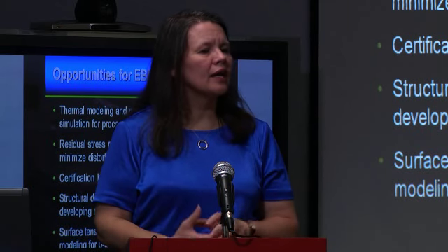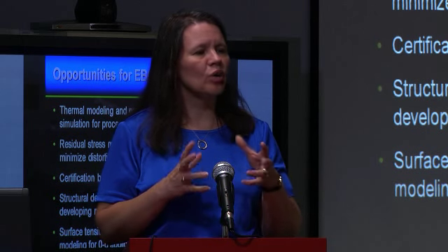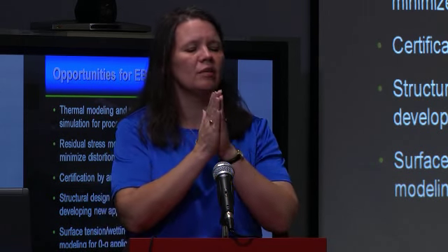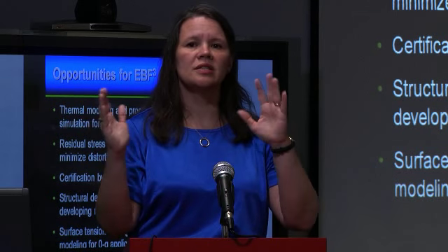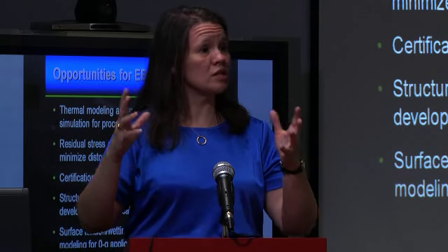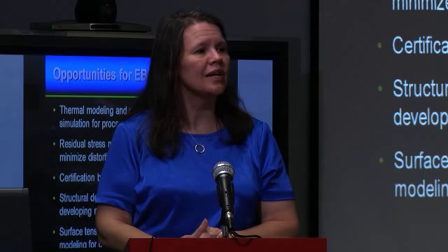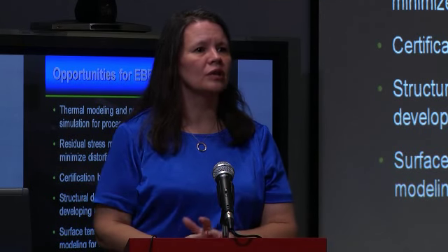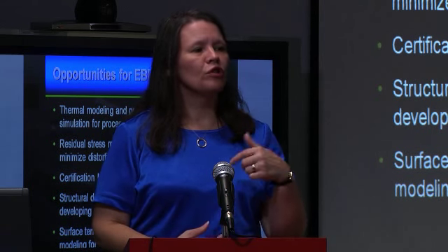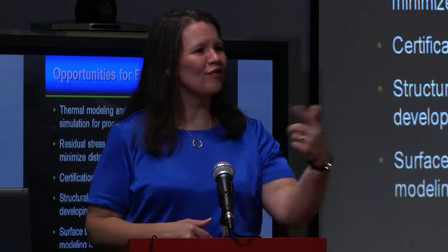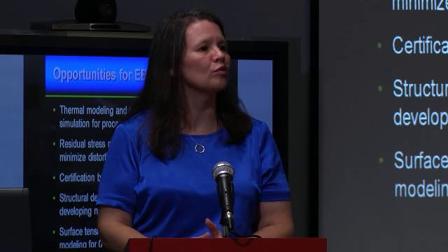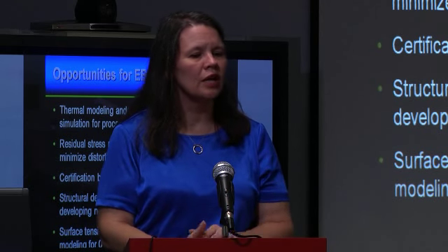We're also looking at whether you can balance them. One of the approaches is, can I balance my residual stresses? If I put the plate in the middle and I build on both sides, I can maybe balance those stresses, so that's another approach that's being taken. But yes, you can use heat treatment. That's the first line of business. The first line for ground-based manufacturing would be to take this part afterwards and do a final heat treatment to get the right properties and to stress relieve it.